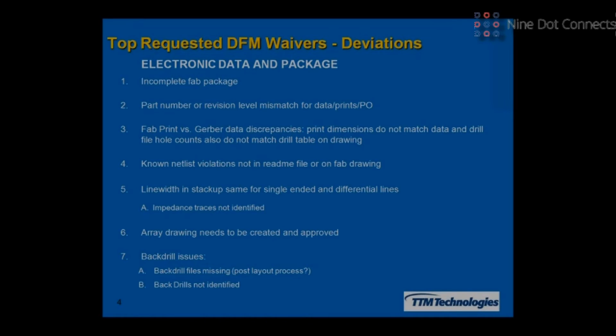And then also back drill to metal. So it's a concern, and I have a slide that shows this pretty good, especially on BGAs, where if you come in with a back drill, you're real worried about the distance of copper around it. And folks in North America versus folks in Asia may have a little bit different capabilities or tolerances that they live with, so they may ask for different criteria.